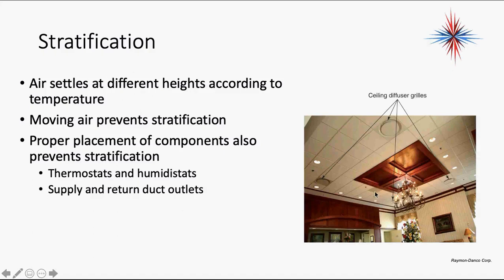So you have a return grill in the center of that ceiling, right next to the wood thing. While my 4 outside diffusers are blowing air sort of in a downward pattern, my return grill is sucking air back into the system sort of in the center of the room. We obviously aren't going to put it in the center of the woodwork because it messes up the woodwork. But the goal is to get it in the center of the room. We have to space things properly.